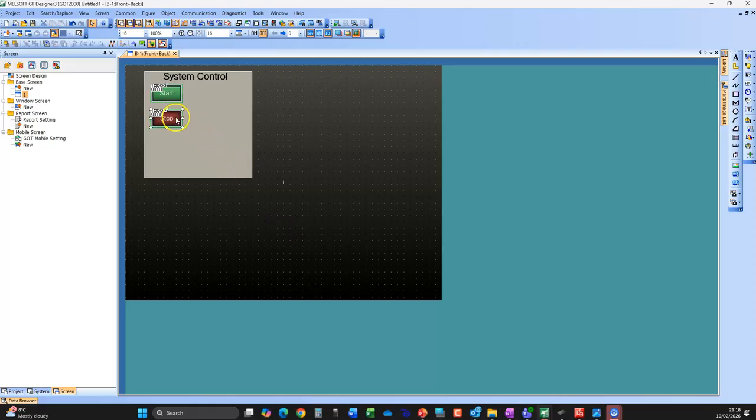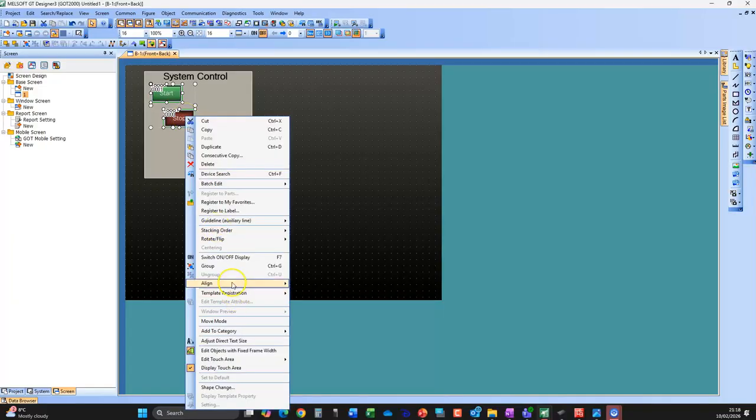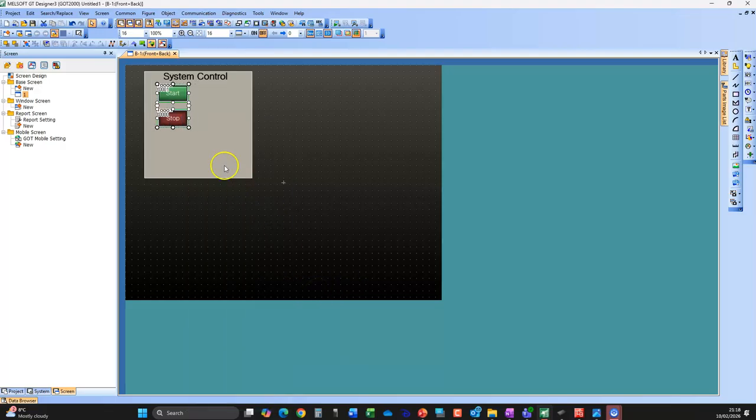Okay, let's just try going out here just to see it. So select, hold down shift, select the second one, and then align, and align the centers. Okay, and then we can move the two of them in unison to wherever we might want them. So that's just the short video just on the bit switch. As I said, I'm going to break these into a couple of short videos where we'll do each kind of component separately. So that's the bit switch done.